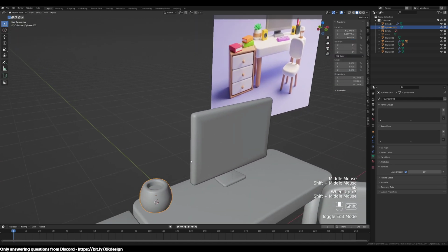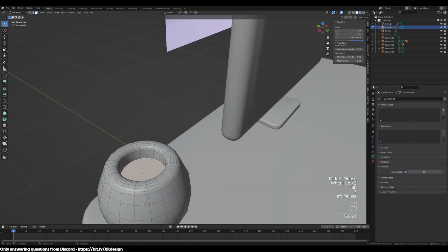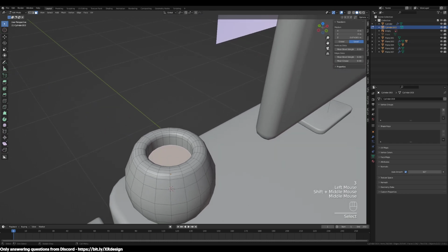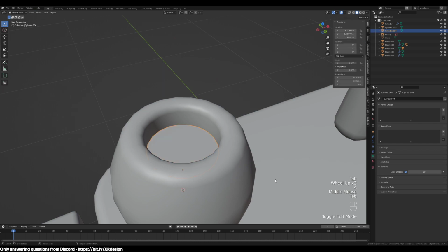And then let's create another object for the dirt. We don't have to, but that's what I'd want to do for this one. So let's select the top face inside, and then just duplicate that. Shift D, hit enter, and let's separate it again, which is P for separate. I don't know why it's that command. And then go back to object mode, select only that top face, and go into edit mode.